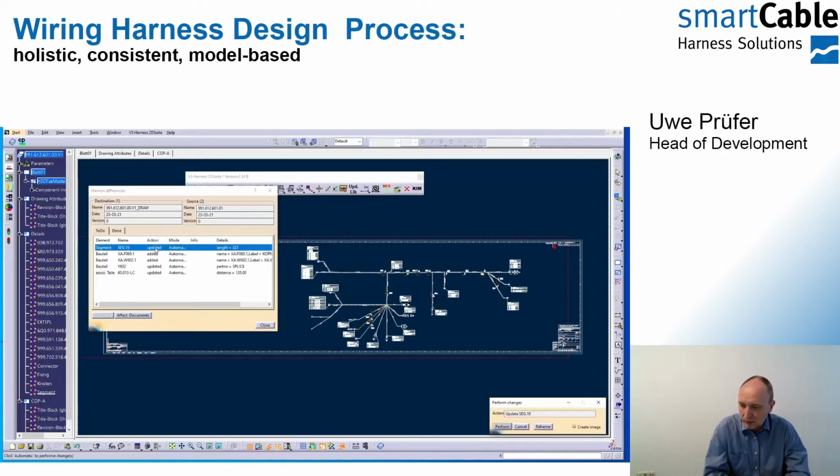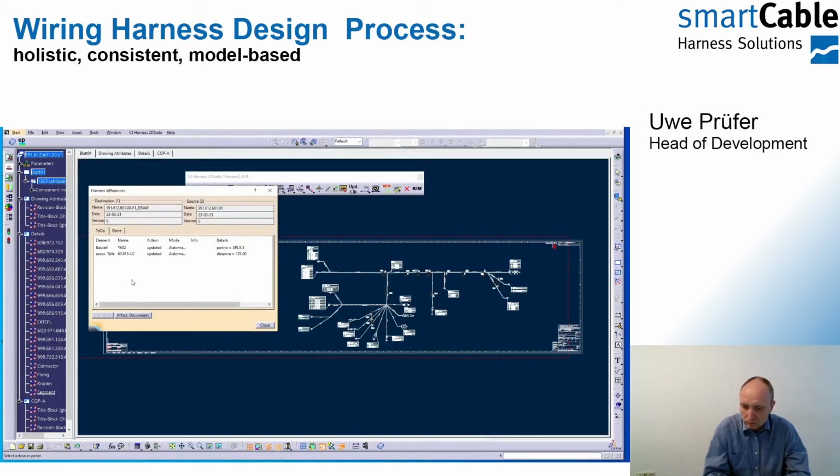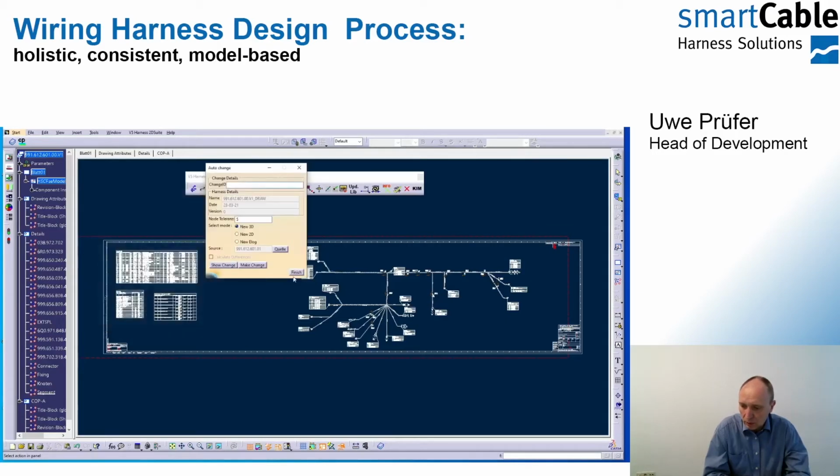I have updated segment length and wire protection, connected the connectors on the ends to the segments, and moved one fixing on a segment to a new position. So if my list is empty, I have no more changes between the versions. I can close that one here, finished.